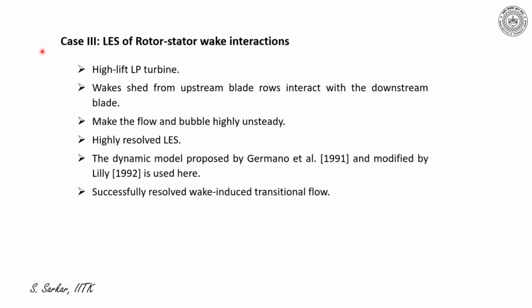In case 3, I have presented large eddy simulation of stator-rotor wake interaction, which is an important issue in multi-stage environments. I have considered here a high lift, low pressure turbine blade, where the blade height is considerable. Wakes shed from upstream blade rows interact with the downstream blades and make the flow and the bubble forming on the suction surface highly unsteady. The periodic passing wakes interact with the boundary layer and thus the flow is really enriched in this case.